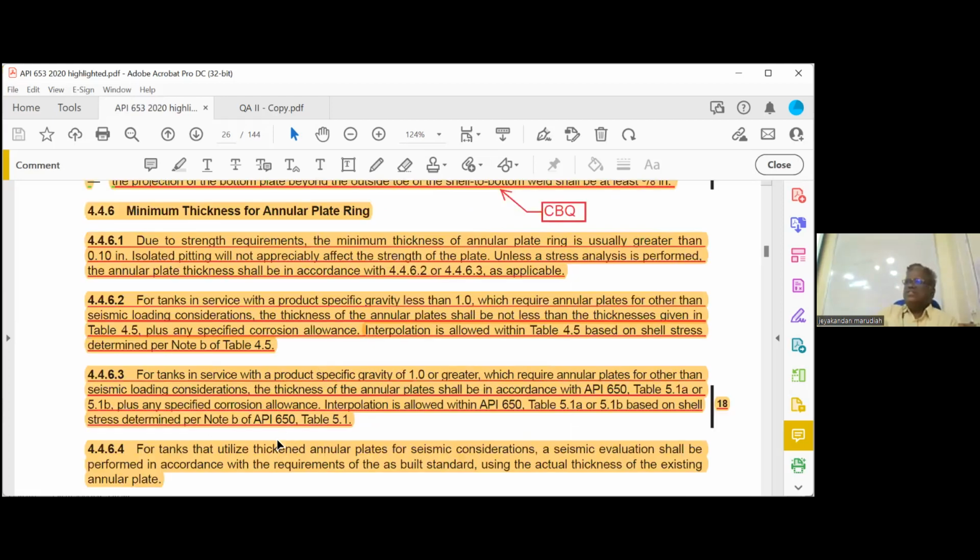There are other things. Where is this 0.1 inch mandatory? If you take a bottom plate, this should be 0.1 inch. But I told you there are 2 conditions. It allows 0.05 also, half of this. One condition is when you have a thick reinforcement lining. Second condition is if you have a release prevention barrier. But in the critical zone, 0.05 inch is not allowed.